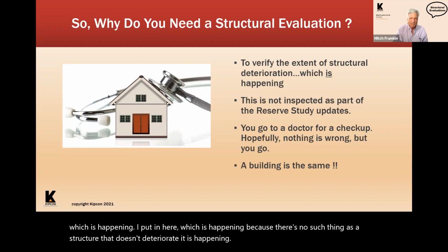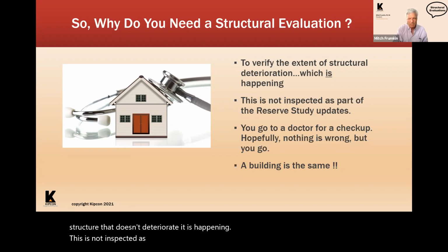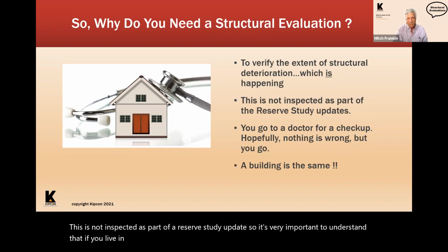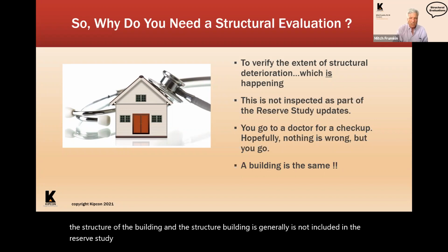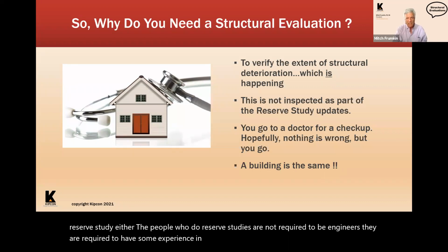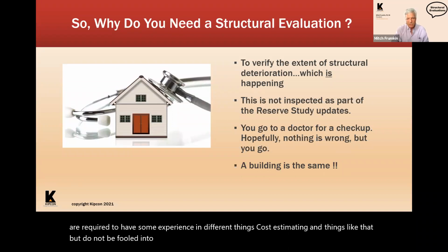This is not inspected as part of a reserve study update. So it's very important to understand that if you live in a community association and you have a reserve study done, it's not looking at the structure of the building. And the structure of the building is not included in the reserve study either. The people who do reserve studies are not required to be engineers. They are required to have some experience in different things, cost estimating and things like that. But do not be fooled into thinking that just because you have a reserve study, that it's checking the structure of the building.